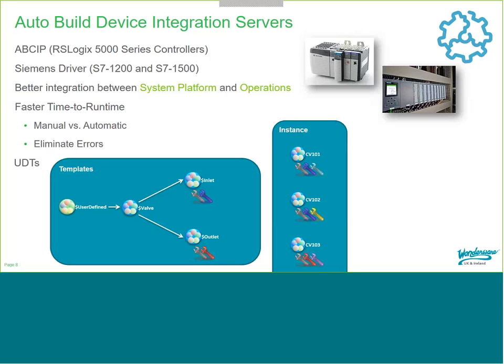Now, one of the advances of Update 2 for System Platform 2017 is that they've introduced object alias names. Obviously when you're pulling in items from PLCs, they might not have friendly naming conventions, so it's something that not everybody would understand. The purpose of this alias naming is that now we can change it to something that everybody does understand. So that is one way to get everything into System Platform, and then you've got to do things like associate graphics with those templates, and then present them in your visualization client in some way.